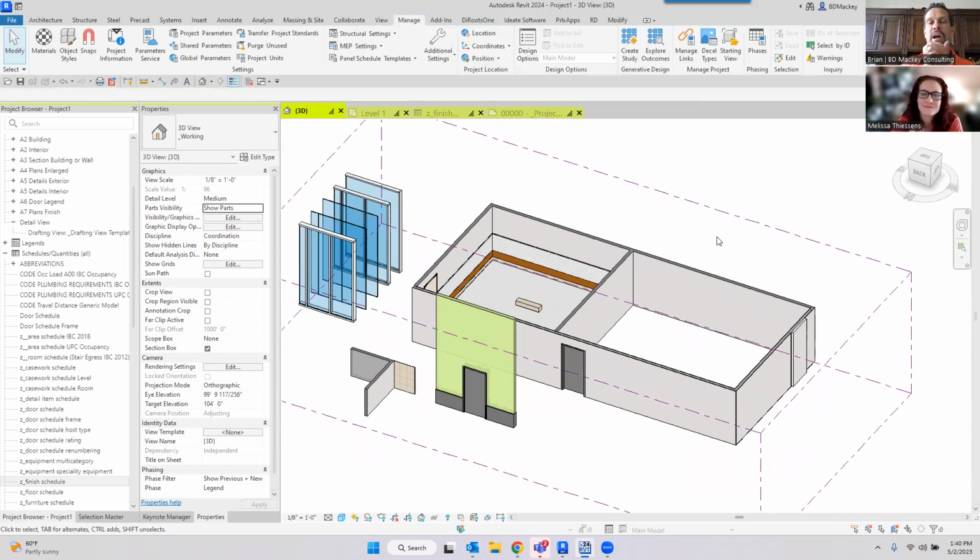It's like, hey, a contractor could take an architect's model and break that concrete wall going up the shaft into parts by levels, and then they could start using that in their own Revit model, or take that concrete slab, another great use for it, divide it into parts and start showing all your control joints. So I have structural engineers who model one slab, break it into parts for just showing all the construction joints. So you could do it that way as well. And that was the theoretical thing of Autodesk when they did it, is, ooh, you can break this into parts. It's part of our construction thing they did way back when. Yeah, I do remember them parading that around.